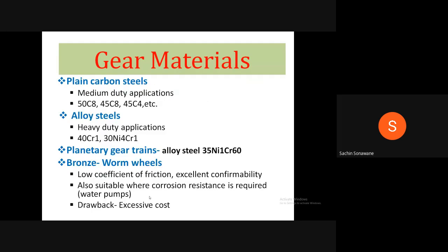Then plain carbon steel. Plain carbon steels are used for medium duty applications. Plain carbon steels are 50C8, 45C8, 45C4.